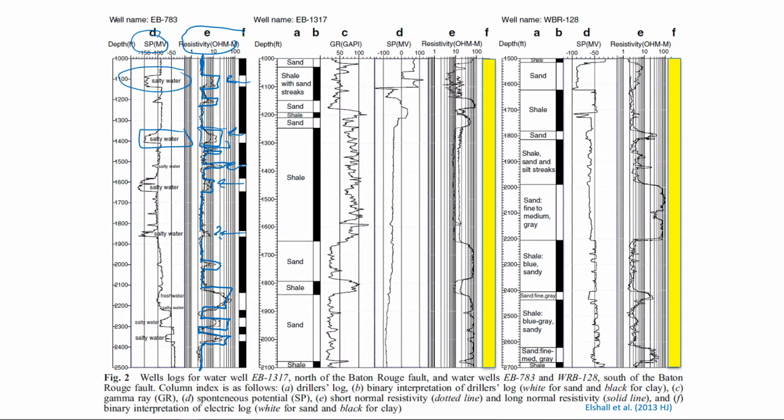Yeah, this is also sand. We interpret this as sand. This is sand, and you see, this is clay. So this is impervious. Water does not flow here. This is impervious, and this is pervious.